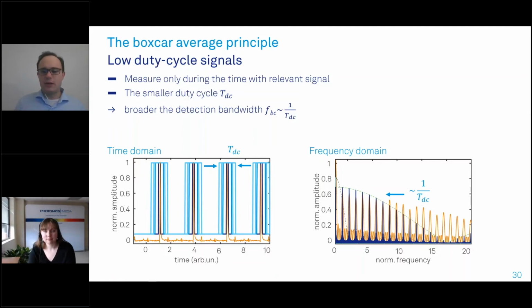Assume you have a 1 kilohertz system. This would mean you only need a measurement bandwidth up to a megahertz to capture 1000 harmonics. And this would never work that easily with a lock-in amplifier. But for up to, let's say, 8 harmonics, you could do it also with a lock-in amplifier, yes.